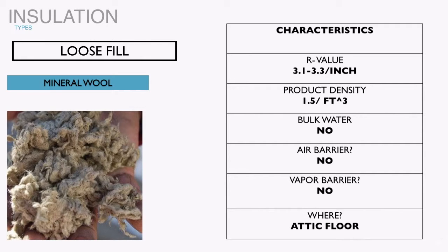It won't shed bulk water, and it does not serve as an air barrier. It does have sound insulation properties, which a lot of these products do. We're not really talking about sound insulation, but certainly bats, spray foam, and fiberglass products have sound insulative properties. Worth mentioning, but not in this context.